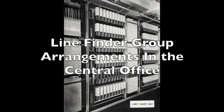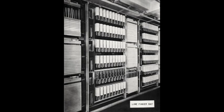Here's what the line finder groups look like mounted in a lineup of line finder bays in a central office. In a number 1 step-by-step office, these bays are 11.5 feet high and about 7 feet wide and can each mount 3 line finder groups. Try to imagine how much floor space was taken up by step-by-step equipment. A large 50,000 line office would have somewhere around 24,000 line finders, selectors, connectors, and miscellaneous switches. The line finders alone would require 84 of the bays shown here.